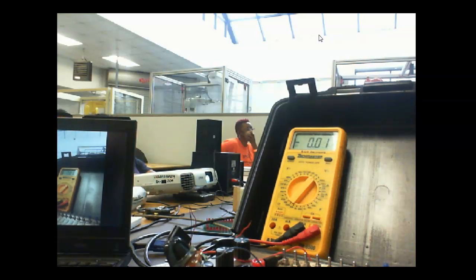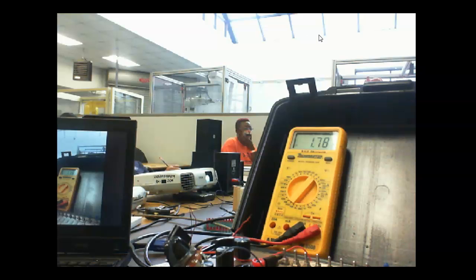Now when I measure my emitter with that resistor open, it's measuring the same as my base. In fact, it went up a little bit. Now why am I measuring anything at all? Because I still have a junction between my what? My base and my emitter. But there's no current flow through that junction now. So the 0.7 volt is out the window because there's no current flow through it, right? You understand? So this guy here is measuring the same as the base, and the only thing that could happen is that that resistor was open.